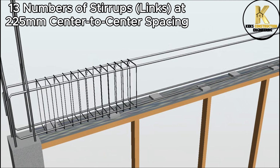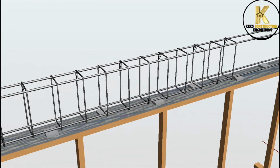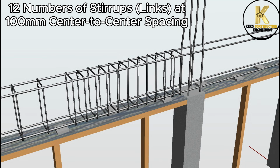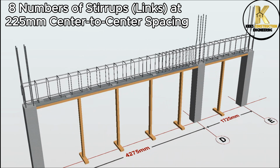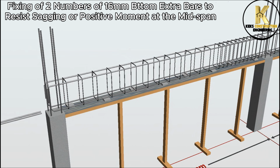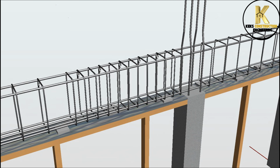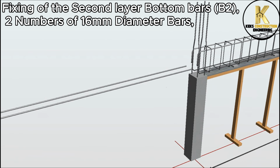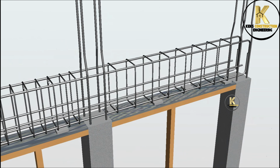13 numbers of stirrups links at 225 mm center-to-center spacing. 12 numbers of stirrups links at 100 mm center-to-center spacing. 8 numbers of stirrups links at 225 mm center-to-center spacing. Fixing of the second layer bottom bars B2, 2 numbers of 16 mm diameter bars.